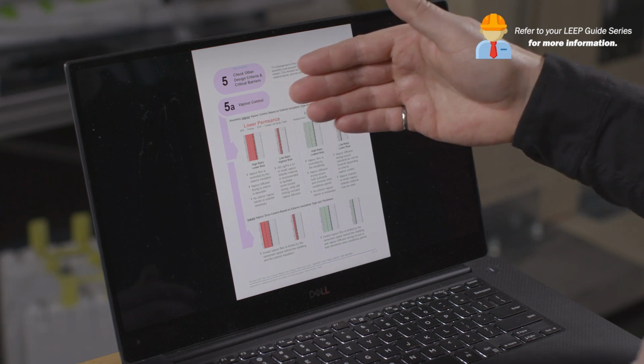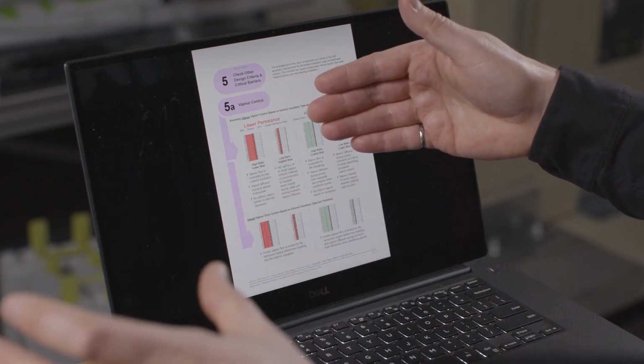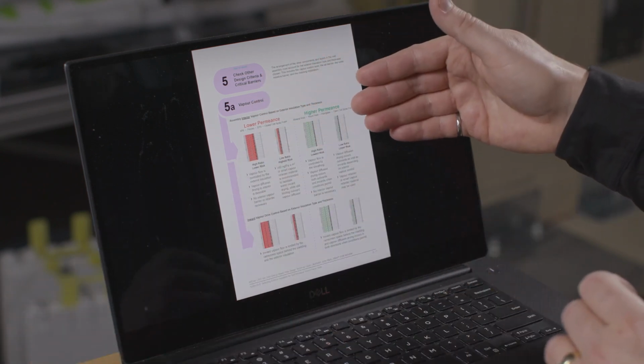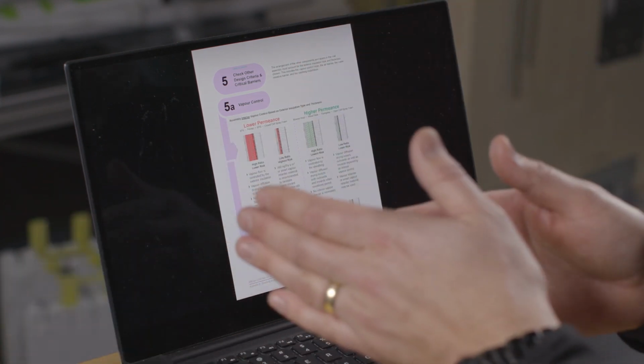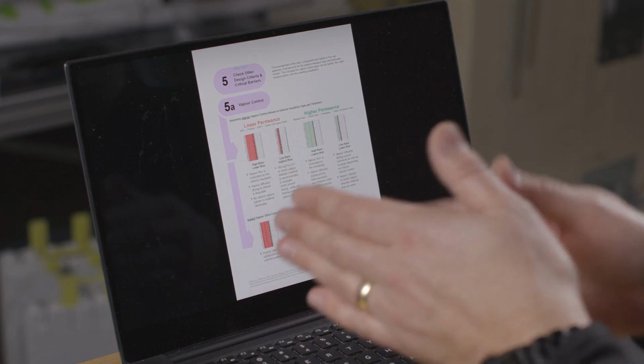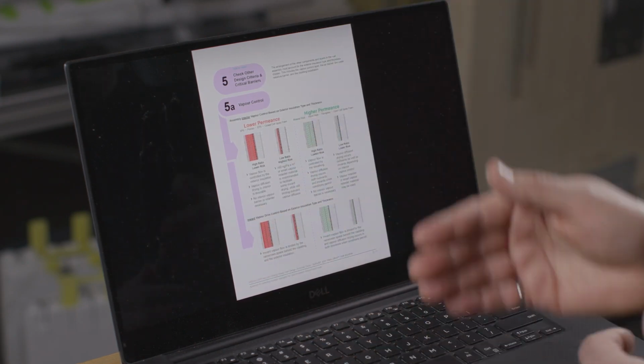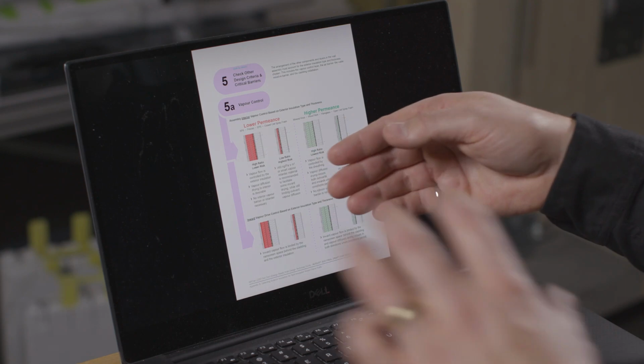The first thing with vapor control is we have low permeance insulation and then we have high permeance insulation. On the left-hand side, we have low permeance insulation with high ratios and low permeance insulation with low ratios. And the vapor flow control guidance is different. If you have a lot of exterior insulation, the exterior insulation is entirely controlling the vapor flow. If you have a little bit of insulation, you might not have enough insulation to warm that sheathing up enough, and that's what the ratio is looking at, and therefore you may need some vapor control on the inside.